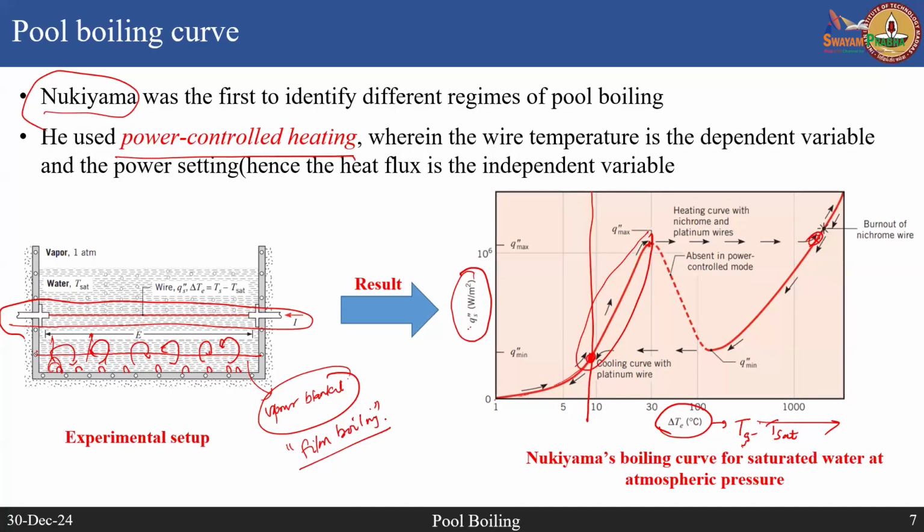and the more benign mode, which is actually more useful as far as boiling heat transfer mechanism is concerned, is called the nucleate boiling. Therefore, you should understand the difference between what is benign and what you are essentially seeking, which is basically operating in a controlled manner where only nucleation happens, and the other extreme, where an uncontrolled heating happens, which is the film boiling, where there is a very thick film of vapor blanket, and because of which, vapor has very poor thermal conductivity.